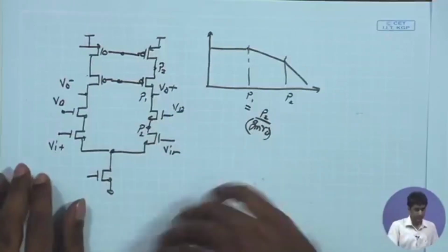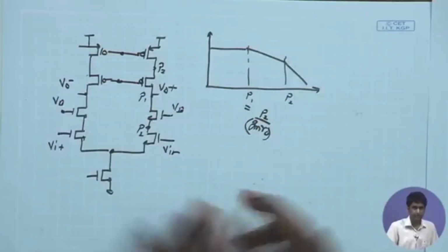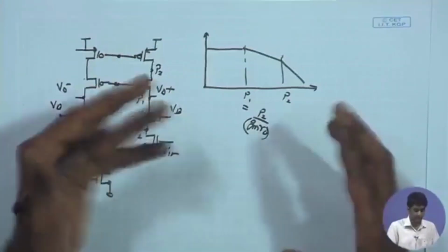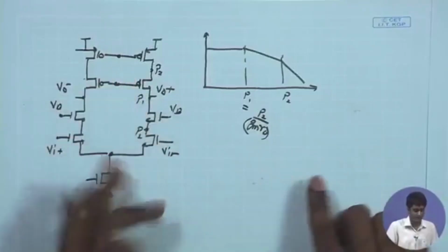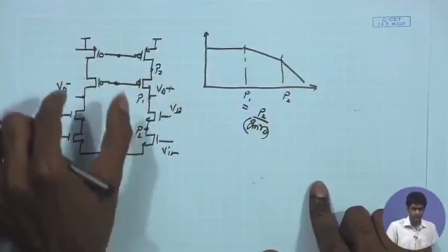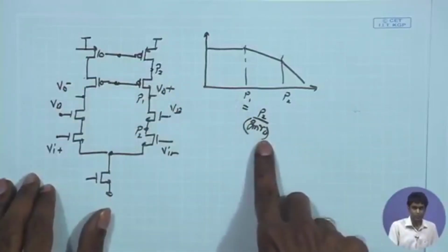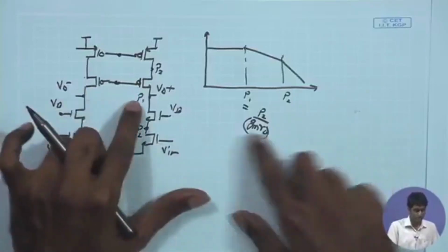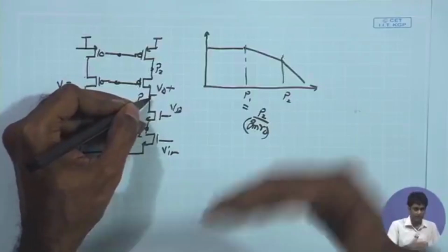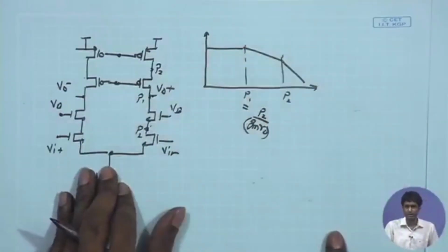And in the closed loop, if you are trying to build a closed loop amplifier with the help of this, I would once again like to have P2 much lower than P1 by the factor of GMRO whole square. This is the overall gain. So I need that P1 times the GMRO whole square, that is the open loop gain of this amplifier, equal to P2. So I need to put an additional capacitance of this value, or I need to make sure that the ratio of the added capacitance over here upon the parasitic capacitance over here is also having a ratio of GMRO.